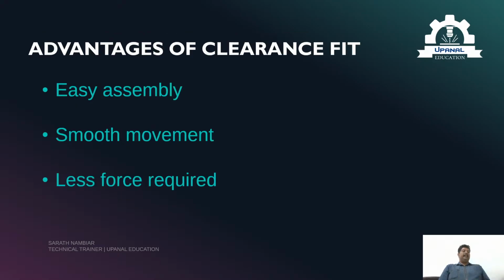Now, what are the advantages of clearance fit? The advantage of clearance fit is, one, parts can be assembled just by hand. We don't need a hammer or any special tools for assembling. The movement will be smooth and free, and there will be less friction. So this will make maintenance and repair easy.